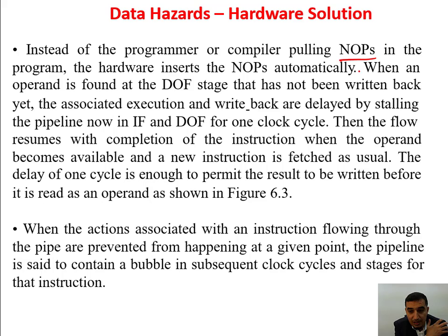Now, instead of the programmer or the compiler putting NOPs in the program, we need to do it automatically using the hardware solution. With the hardware solution, we want to do all of this automatically. So when an operand is found in the decode operand fetch stage that has not been written back yet, the instruction fetch and decode operand fetch are stalled for one cycle, and then the flow resumes with the computation of the instruction when the operand becomes available.